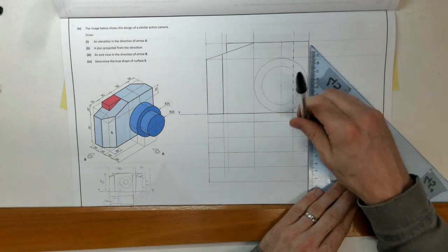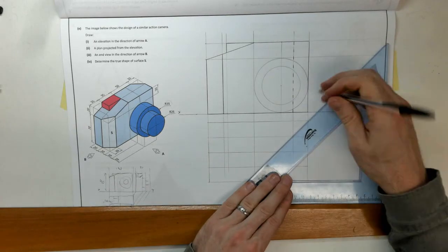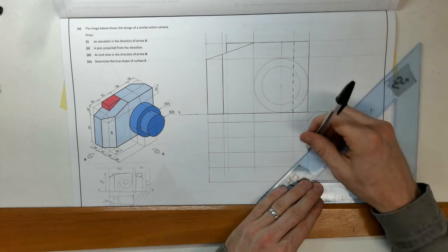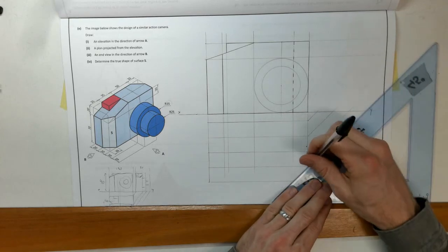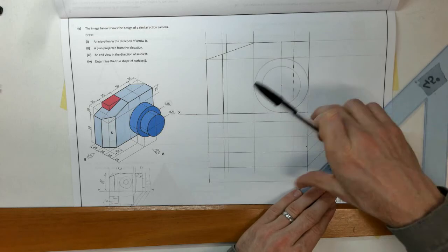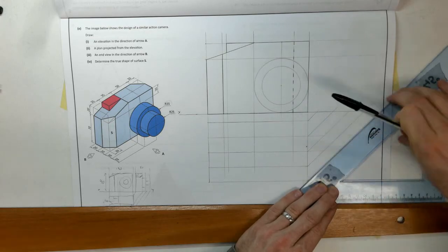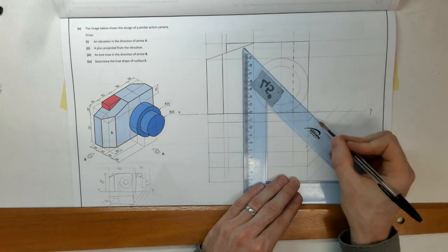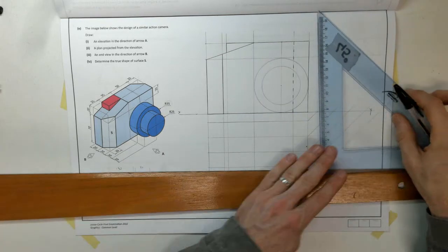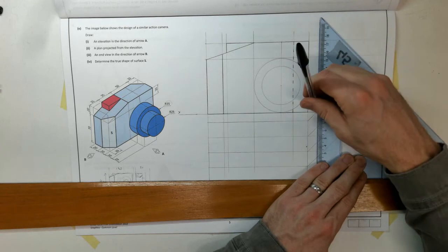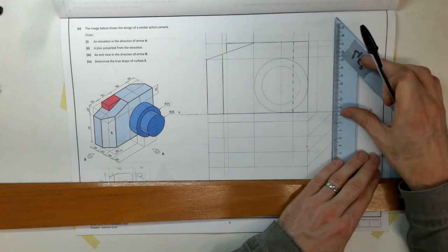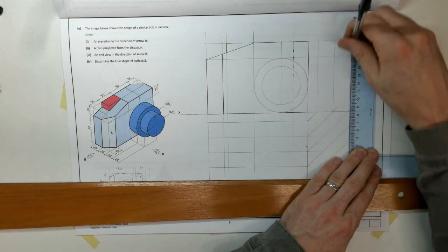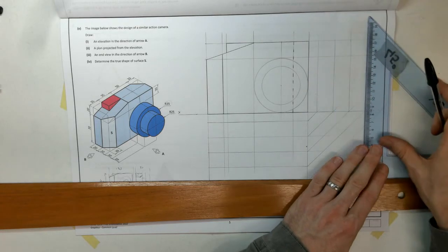And seeing as I've marked those off, I'm also going to just project them up at 45 degrees. As I said, you use a method that your teacher uses with you in class every day, which could be rotating these distances. Or it could be a 45-degree line here and you come out to meet it and directly up. All of those methods work. And I'm going to extend these up then, because I'll use them later for my end elevation.